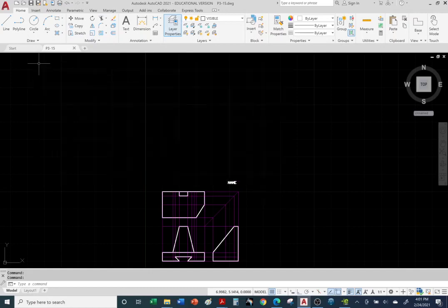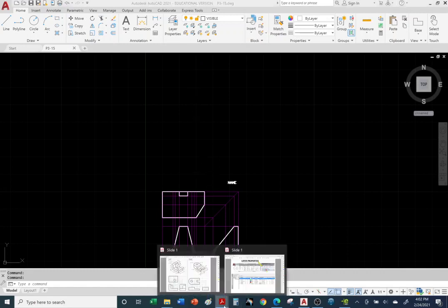All right. Let me go ahead and turn off layer properties. And again, you'll be creating your own from scratch later on. Okay, if you want to jump between layers, this is how you do. You go to the drop down. Okay, to jump from one layer to another. If you're going to create center lines, you want to turn on the center lines layer, or I should say activate it. If you're going to create wide visible object lines, then activate this layer. Okay, or select this layer. Okay, so let's go back to the lecture.